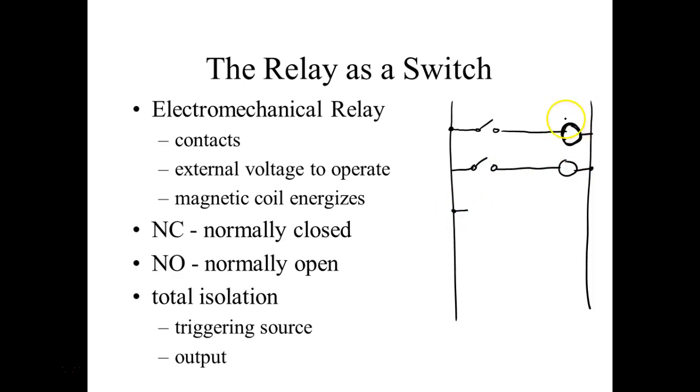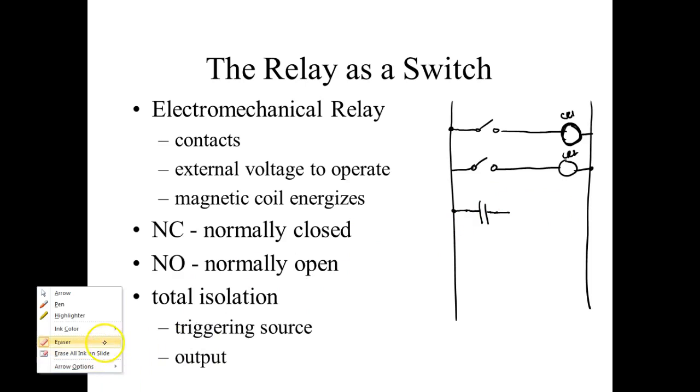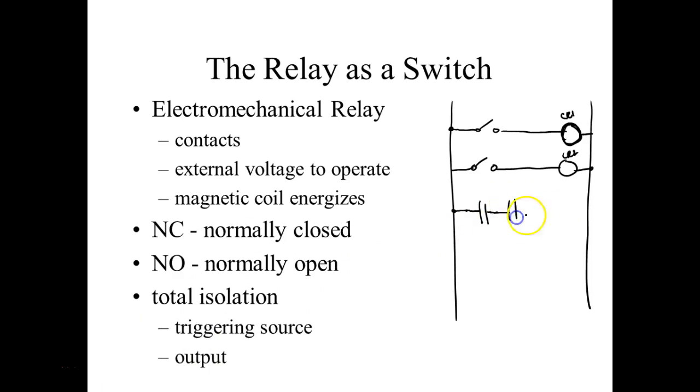Then what we do is we give these relays names. So right now, let's call this CR1 and call this CR2. And then the contacts or the switches that are controlled by that, we draw like this. And what do you think that's a symbol for? Relay. Yeah, this is a light, but it doesn't have a line. And let's say I assign this contact to CR1 and I assign this contact to CR2.